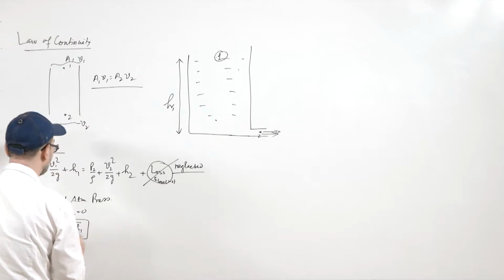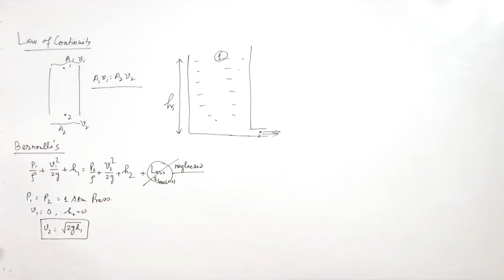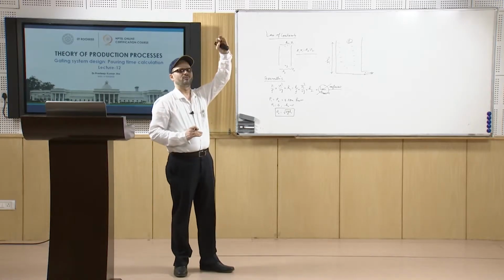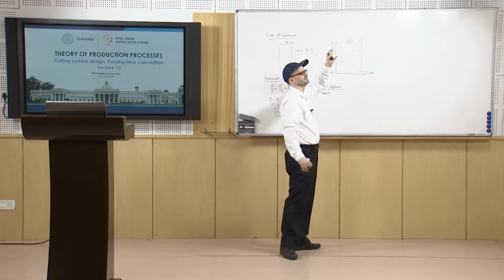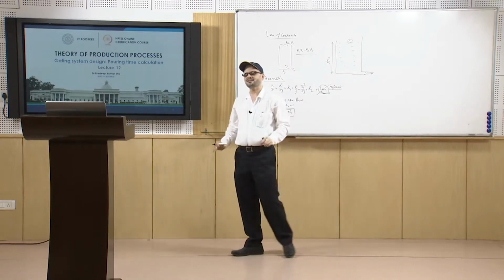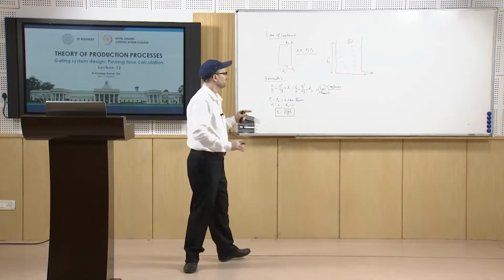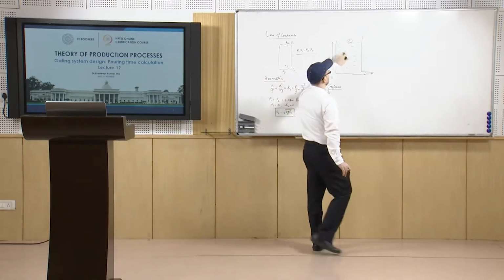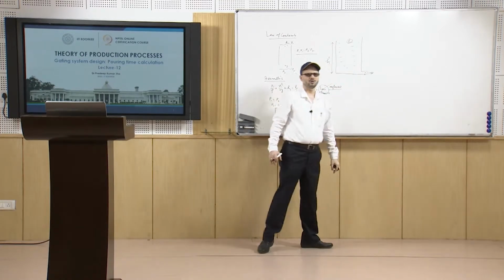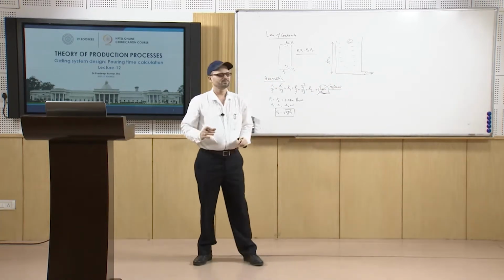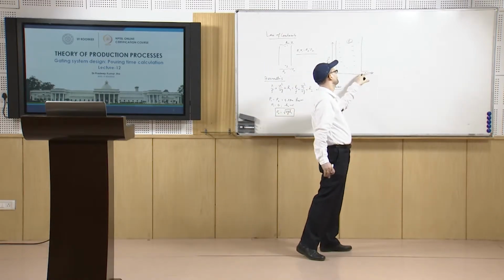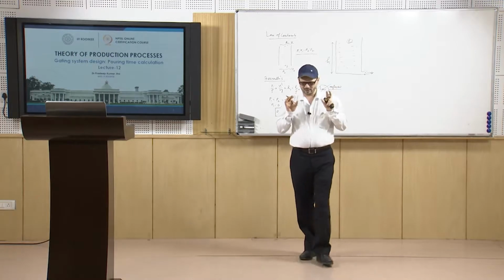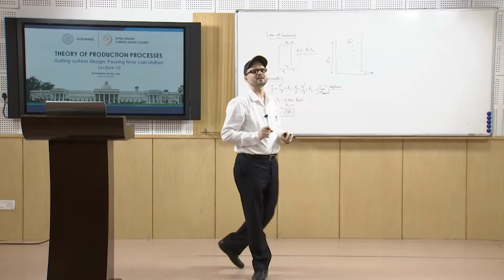So, using Bernoulli's equation, you can see that when a liquid falls from a height h, or height h1, the velocity attained when it comes out of the orifice or nozzle is found as follows. In the case of casting, you will have the sprue well or the level of the gate from where the metal will enter into the cavity.